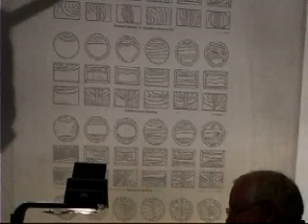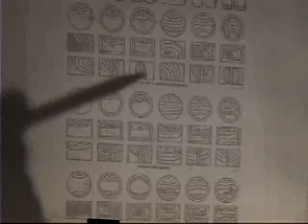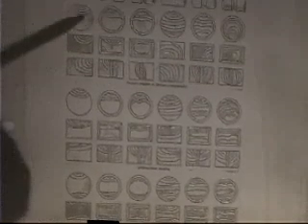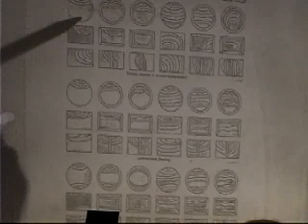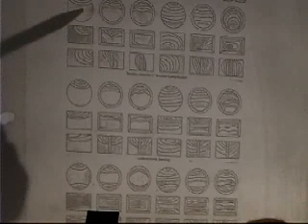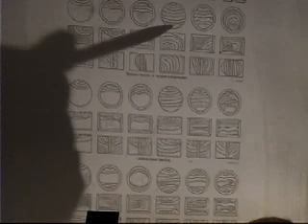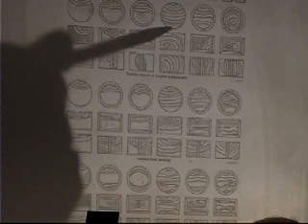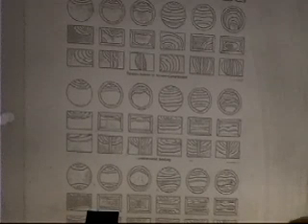This is high nominal stress. You notice the large final fracture area of this guy? Whereas over here at low nominal stress, you have, actually on low nominal stress, well, let's do this one, because that one, they don't even leave much of anything to see where the final fracture is. Here you have a large final fracture area over half of the sample. This is a very small fracture, okay? And there's all kinds of things you can say about these things.